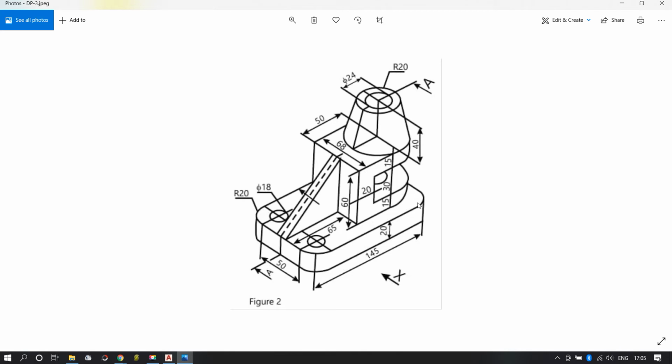You will be first starting with a top view, that means this base plate, okay, then extrude it, press and pull by amount of 20, then you draw these two circles here, then this triangle. Similar figure we have already drawn, I think. And here also you need to divide into two parts, that means one portion will be this semicircle portion and one portion will be up to this. So this has to be extruded by an amount of 60 and this portion by 15. Then you can simply copy this base portion and keep it here.